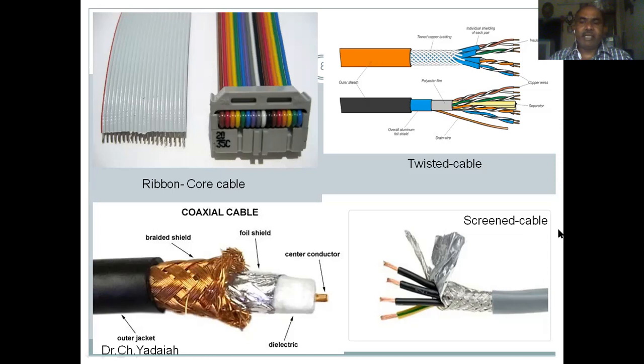Another is a screened cable. Where is a screened cable? If there is an insulation, there are three conductors over which the metallic screen is covered along the total length of the cable. Here the metallic screen, as well as the sheet, should be earthed to nullify the interference of radio frequencies to the normal signals. These are the special purpose cables generally used in our systems.